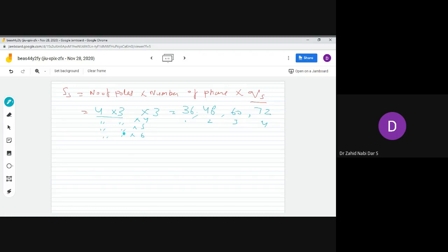Now, in order to judge, this is a small machine. Yesterday we saw a 250 HP machine. This is a 37 kilowatt machine, and usually this type of machine is an open type of machine. Slot pitch for open type slots is equal to 15 to 25 millimeter.